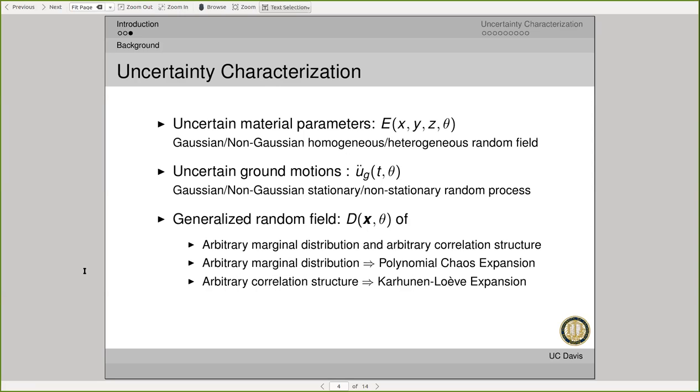But what I'm trying to say is that for the uncertain material, the E is not the elasticity; it's the elastic-plastic stiffness, which inside has elasticity and plasticity, yield function, plastic flow directions, and everything else. So this E, you can think of it as a stiffness matrix, an elastic-plastic stiffness matrix, that is random and spatially variable. Yes, that's true.